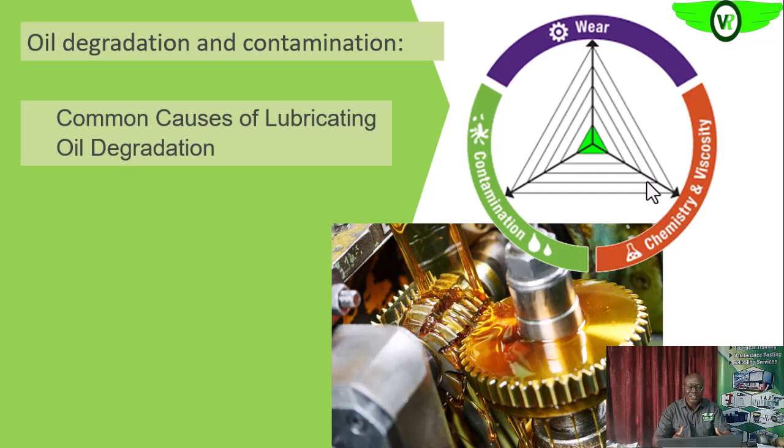That will also assist us in trying to know the cause of such wear. And you also agree with me that the more wear particles we have in the lubricating oil, the more the possibility of increased wear of those internal parts, even the parts that have not been wearing before, because those particles will be sent to those parts, and as the engine is working, it will cause further wearing of those parts, thus increasing the wear.